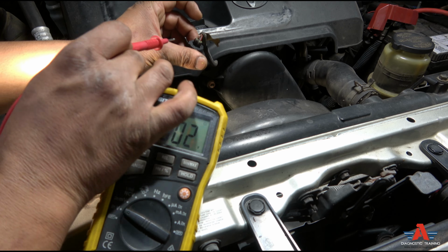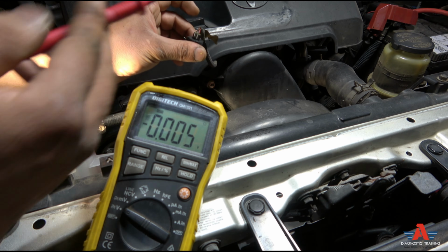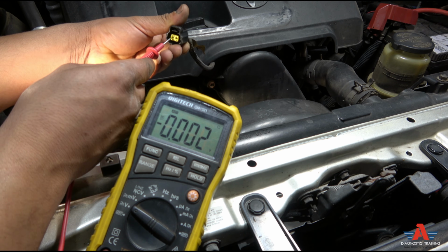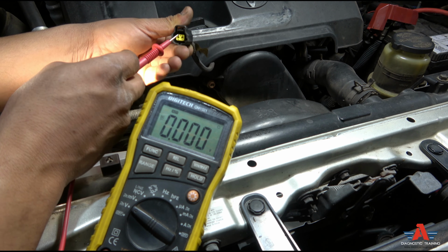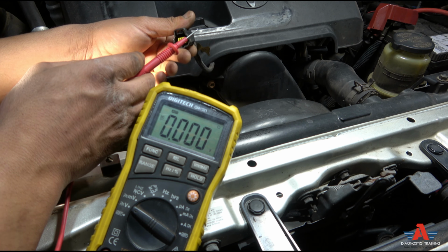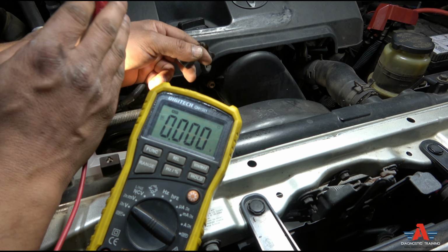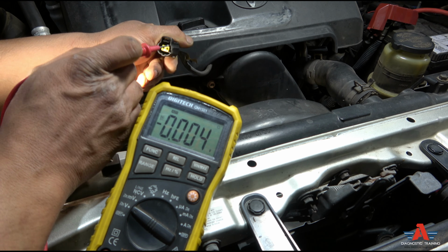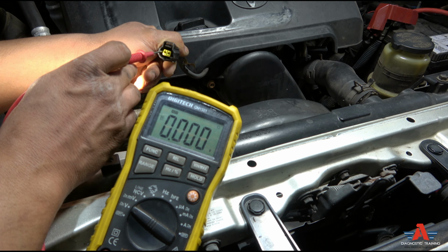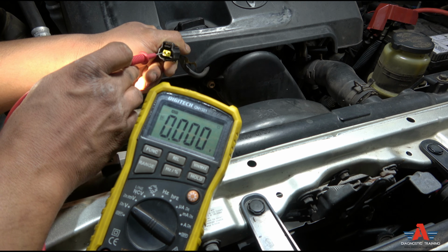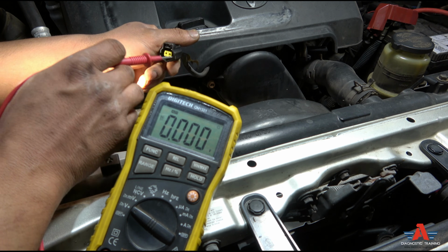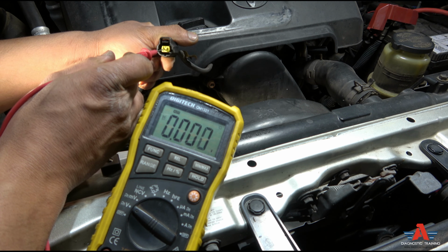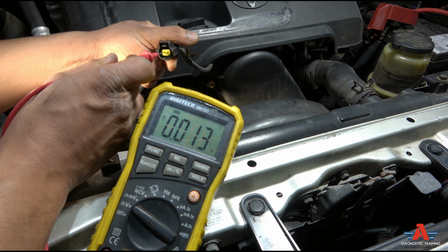At this stage, I don't know which wire is what, which one holds 5 volt, which one holds earth. I don't know, and I don't care at this stage. I'm just going to quickly touch it. Do not spread these terminals, guys. I have seen multiple times on coolant temperature sensors, only coolant temperature sensors, when you have an intermittent fault, most of the time I found these terminals are spread. Someone spread that terminal and now it's not making a good contact on the sensor pin. So just don't spread that. I'm just going to quickly touch it there.